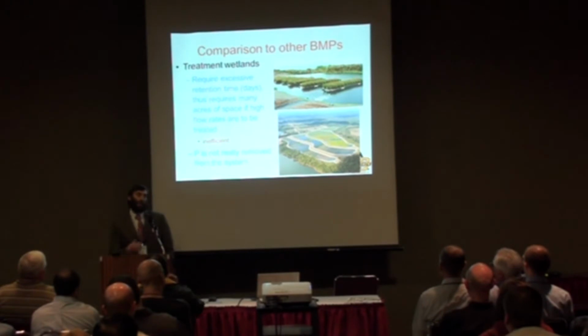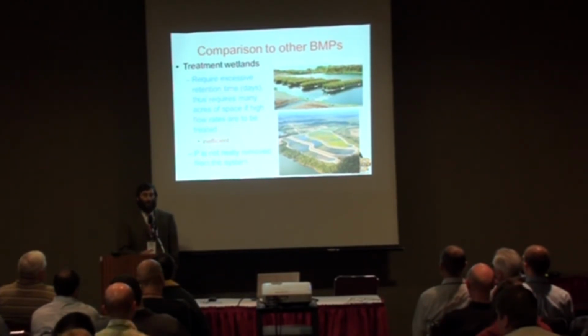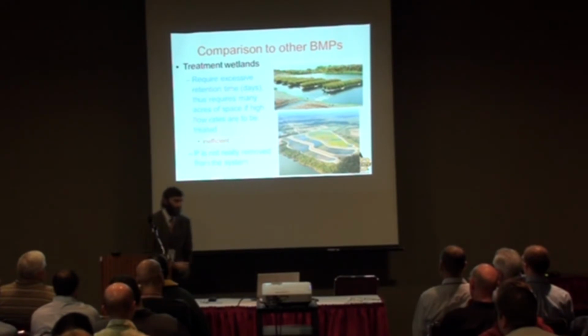And also, unless that wetland is dredged at some point and that phosphorus removed, then it's not truly removed from the system. With these types of filters, once you clean out the material, take it out, replace it, that phosphorus has actually been removed from the system, and it has to be properly disposed of.